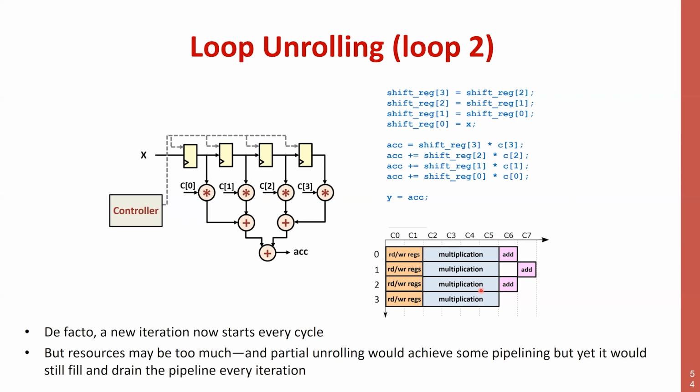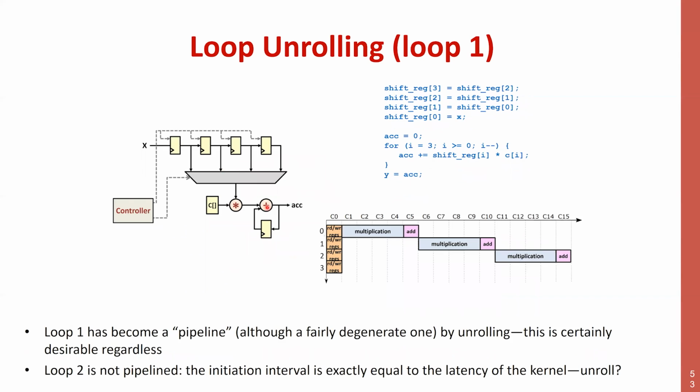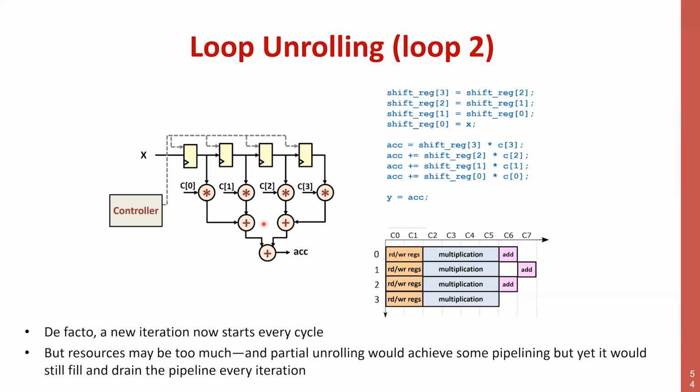You see, by the way, that it's always the same game, right? This is a reduction, and the reduction can be done thanks to associativity with some parallelism, and it is exactly the same trick that we played before with the hardware. And again, I can do it in hardware because I can put the number of adders that I need. Here I need 3 adders. Before I needed only 1 adder. So you cannot do too many of these things in software, or it depends on the context, but in hardware you can put the resources that you want.